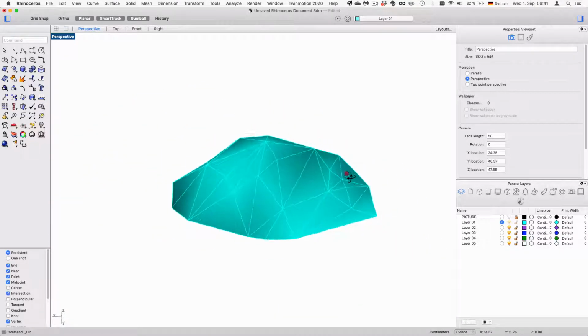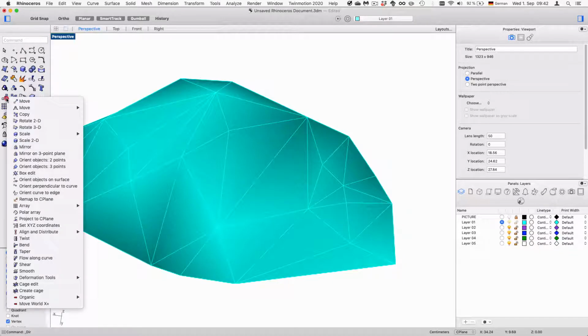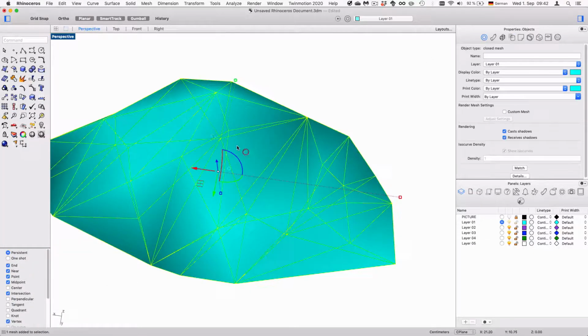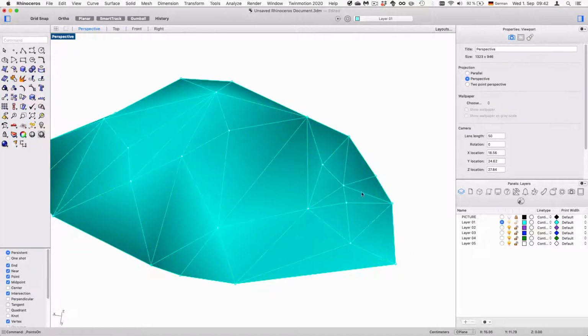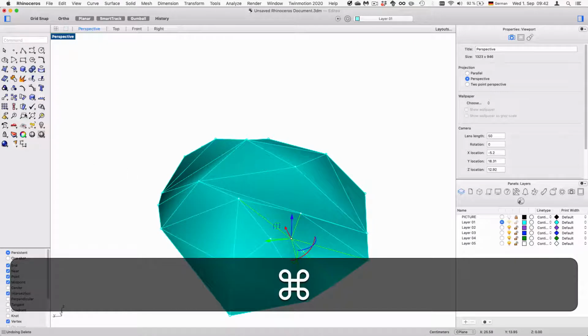And then you might say, well, here it's way too many triangles somehow, or it's getting too complicated. So there's also a way you can delete. If you would just delete a point, let's say you want to delete this point, this will create an open hole here, which is something we want to avoid.